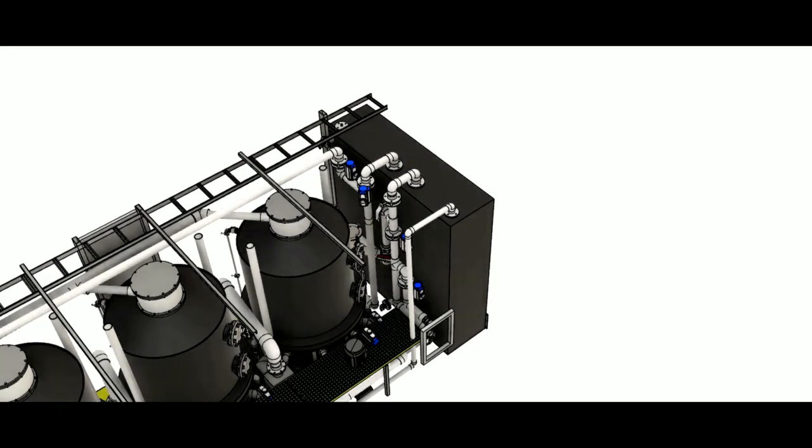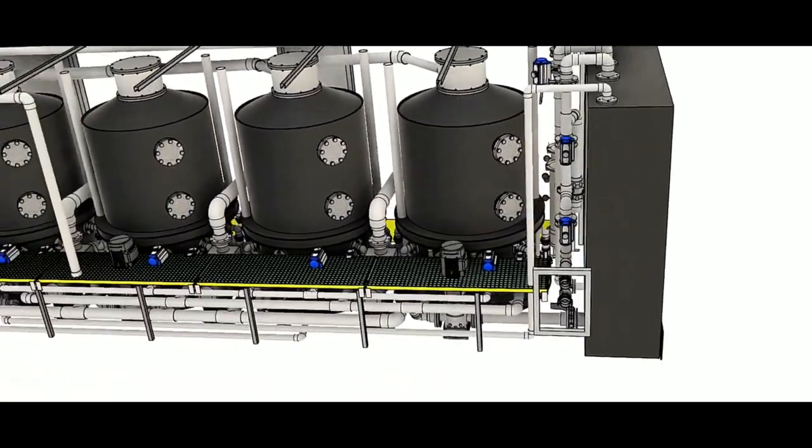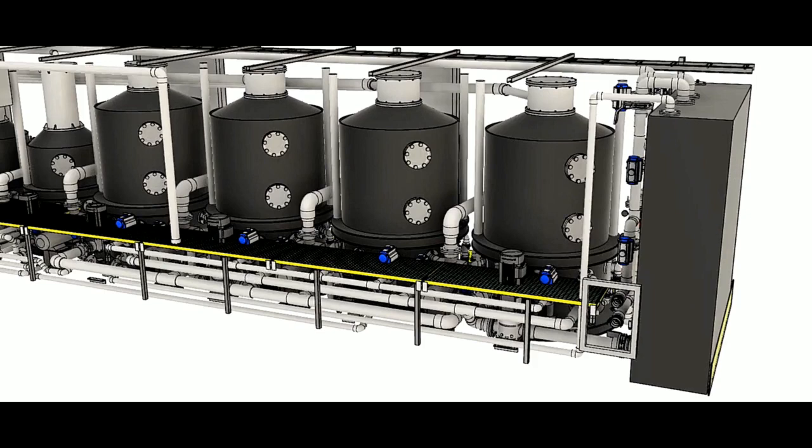So as that right-hand tank fills up, it gets to a certain level, and then it starts one of the 4 fractionators in the fill process. It's about a 3-minute fill time. We're processing for around about 20 minutes, as we showed in the last webinar. The processing times vary depending on the criteria compounds you're chasing. So for us, chasing PFOS, PFOA and PFHXS, we have a run time of somewhere around quarter of an hour to 20 minutes to remove those contaminants completely.